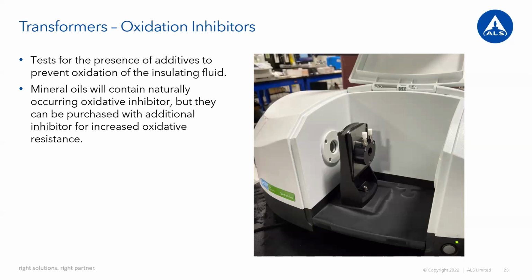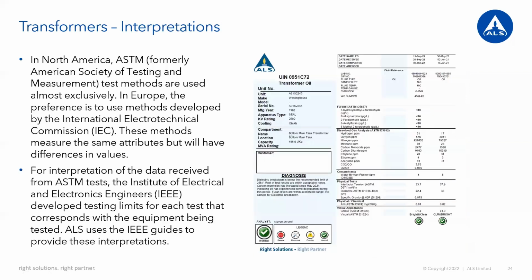Oxidation inhibitors. These are compounds that we put in to prevent the oxidation of the insulating fluid. This will help us with making sure that the acid level doesn't go up. So if the TAN is increasing, then we generally want to see what our oxidation inhibitor levels are, and we can actually add these things later, usually weight by weight using specific routing.